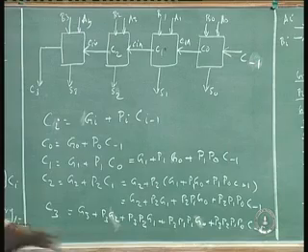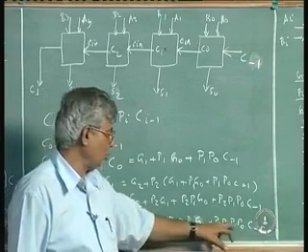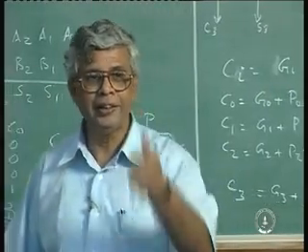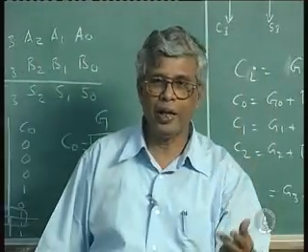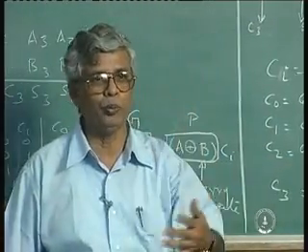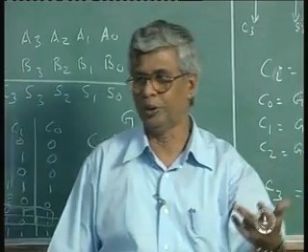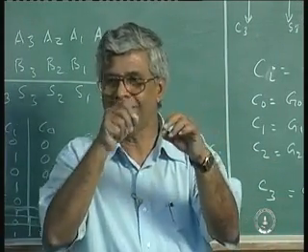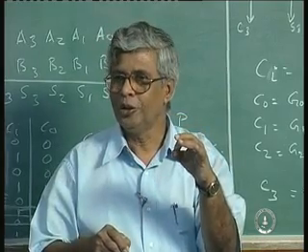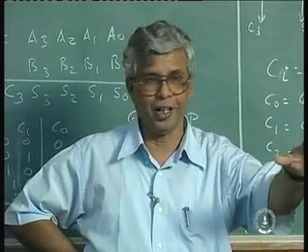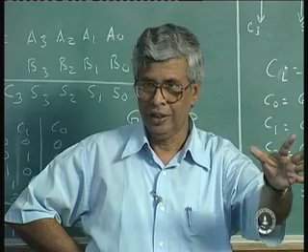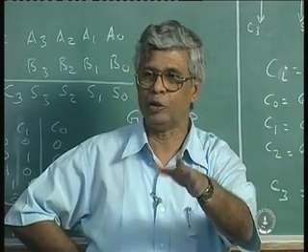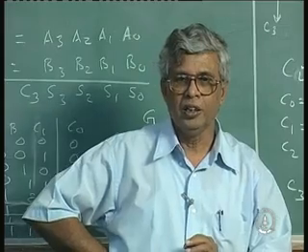Not only that, how many inputs do this get? 1, 2, 3, 4, 5, that will have 9 inputs. So 9 input AND gate, 8 input AND gate, 7 input AND gate, 6 input, 5 input, 4 input, 3 input, 2 input, and all of them feeding into an OR gate with so many 9 inputs. So that will be a circuit which is sort of very unwieldy, and we have not really discussed that. Again, some of those hardware aspects I have not discussed.